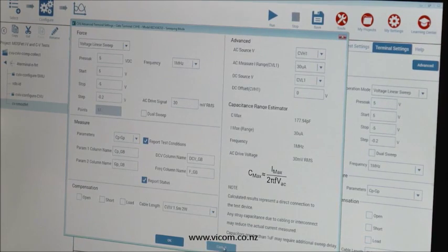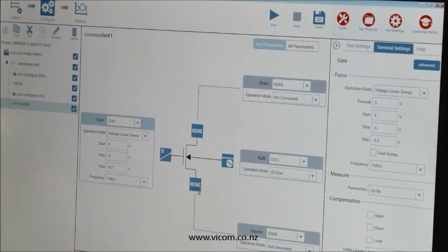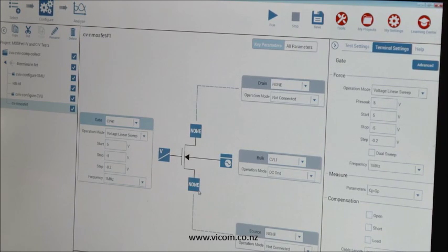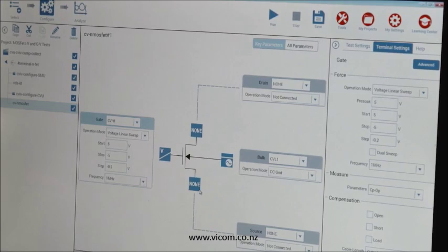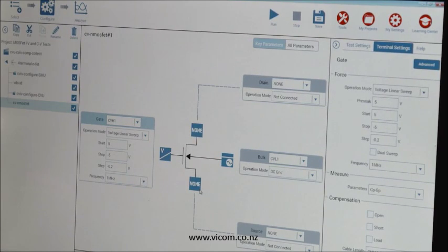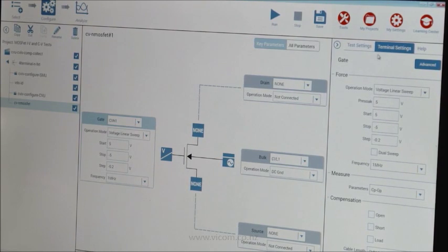What this does for the measurement is you don't have to recable or reconfigure your test setup. You can easily switch where the AC is measured to the least noisy terminal very simply with a click of a mouse.